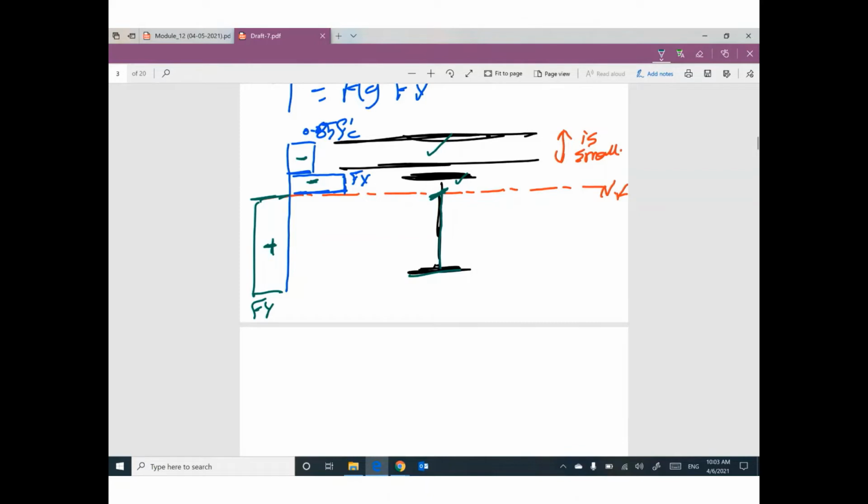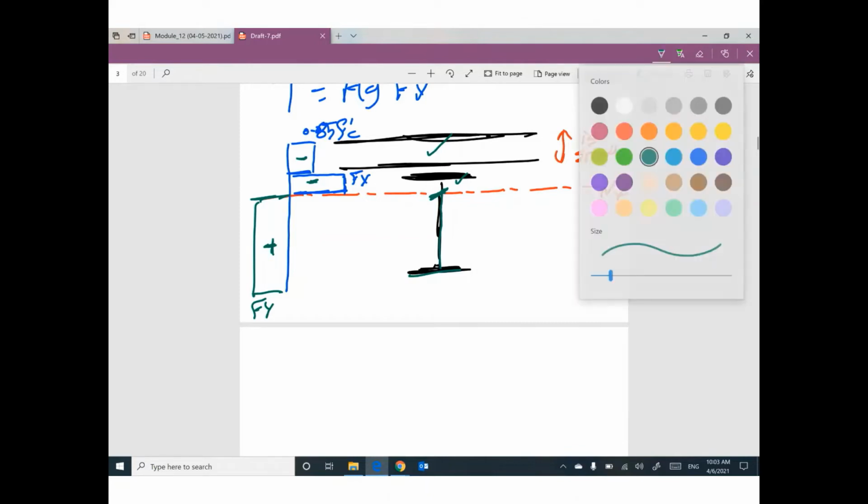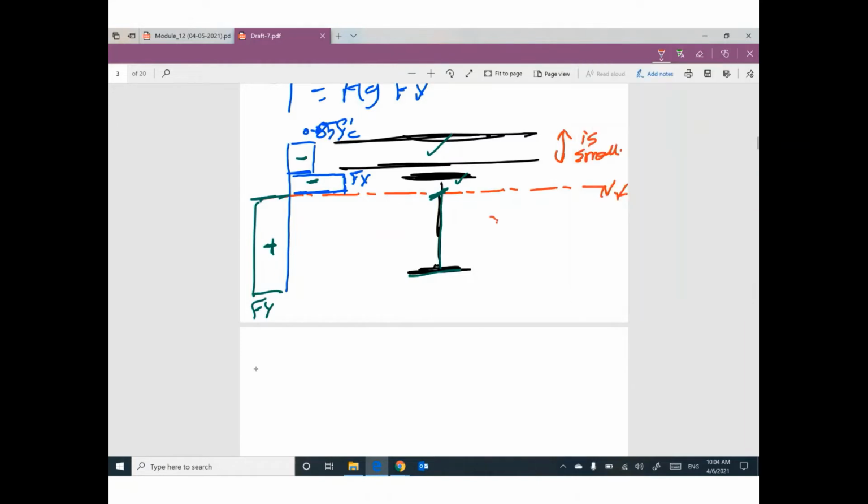One of you will say, hey, what is the problem in this scenario? Is it wrong? I didn't say this. It's not wrong, but we don't recommend it. Do you know why? Because as I told you, we have concrete, which is excellent in compression, and we have steel, which is excellent in tension. So why are you using part of the steel under compression? We don't like this. And remember, steel is very expensive in comparison to concrete, which is very cheap.